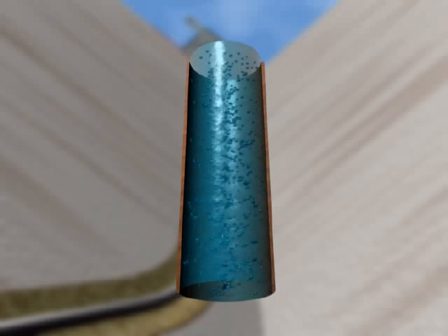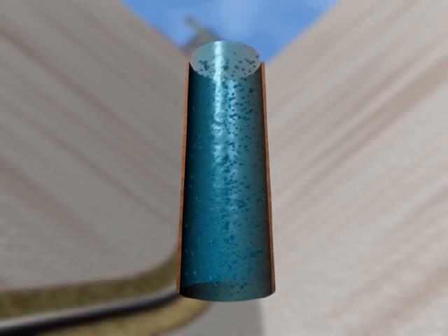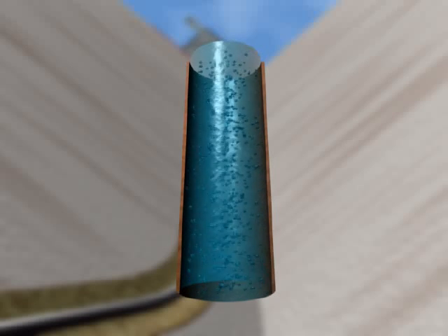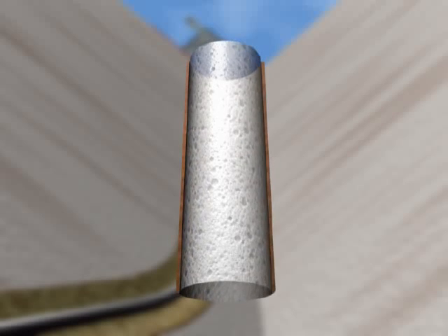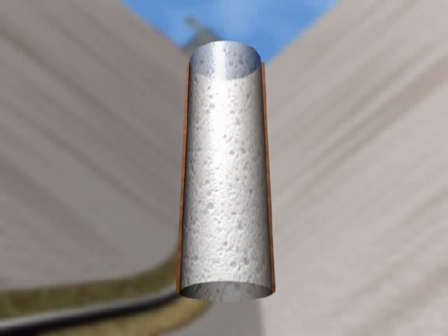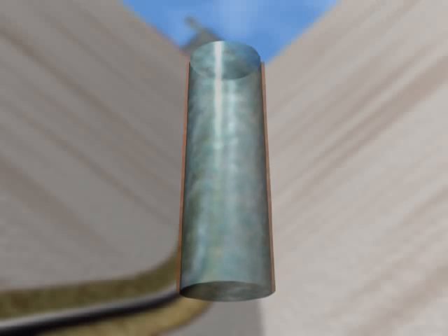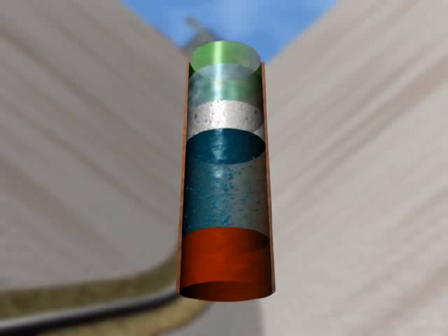To achieve lower bottom hole pressures, a two-phase flow system can be employed. This system consists of a light fluid aerated with a gas, such as nitrogen or natural gas. Foam systems generally consist of water and a surfactant. At the low end of the scale, mist or air-based systems can be employed. Each of these fluid systems requires a different surface setup.